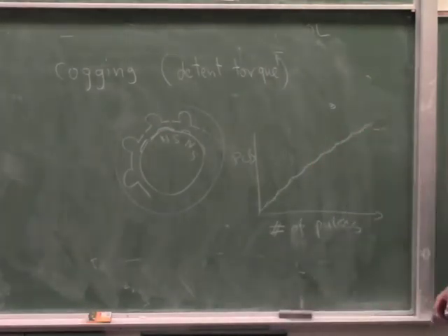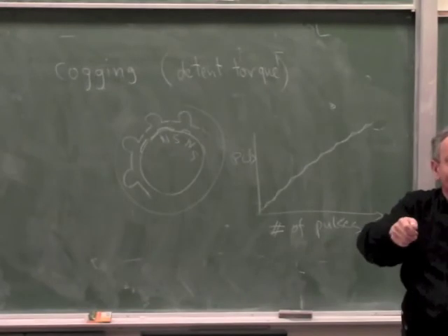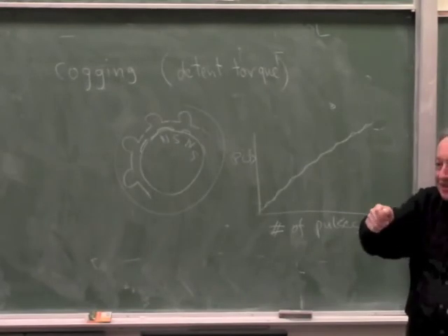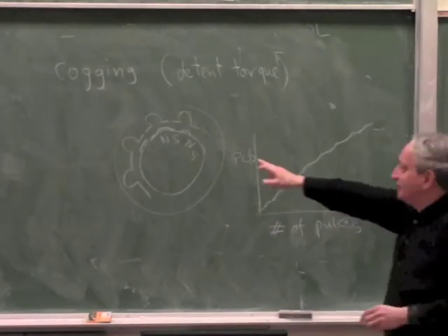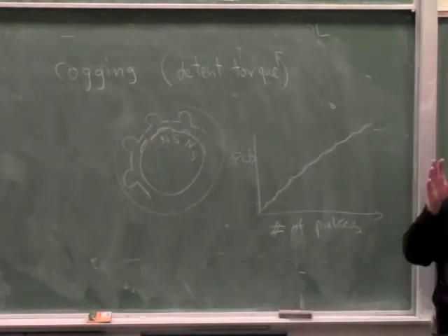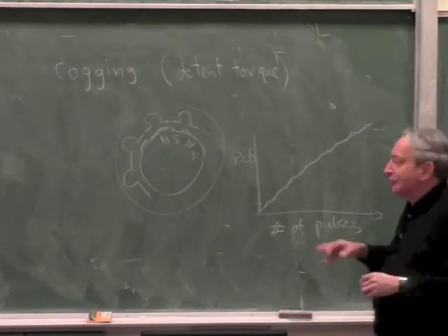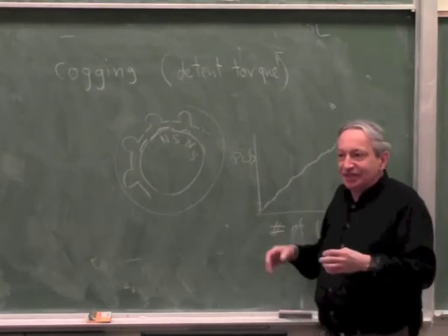Okay? The same thing you feel when you take a stepper motor and you turn it without power. You feel it does tick, tick, tick, tick. It doesn't go smoothly because you feel those natural positions. Okay? So again, if it was perfectly laid out inside and the flux was perfectly distributed, under power it wouldn't have that. But there's always a signature.